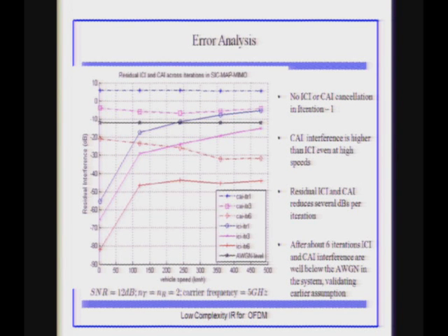Remember, it's also the 256 FFT, right? That's right. Most of the systems like LTE use 1024, 2048. 256 is pretty low for the current systems. I think it is about packing more carriers more tightly.